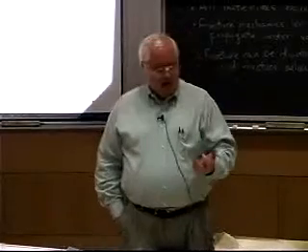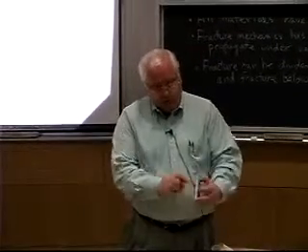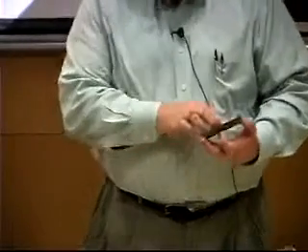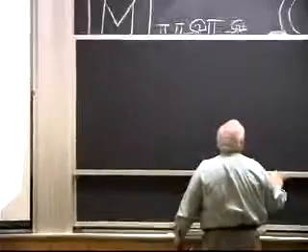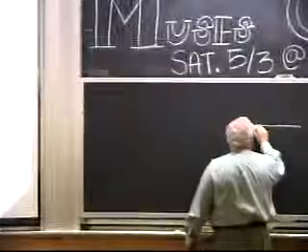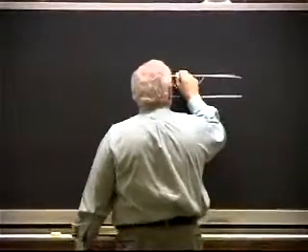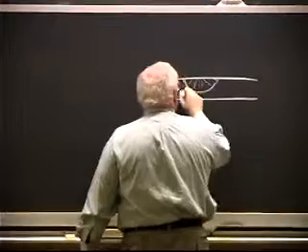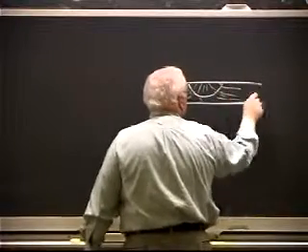It failed in fatigue. I looked at it in my dining room and I said, oh, well, there's the fracture origin right there. When I pass it around, you can see the fracture origin because I marked it right here. If you look very carefully, you'll see a little thumbnail notch, which is typical. And you actually can see it in this light. The other day in my office, which has brighter lights, you couldn't see it, but there's a little region where you kind of have radial flaws growing there, and here you have the fatigue crack lines.